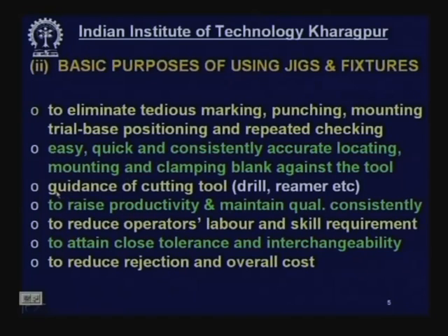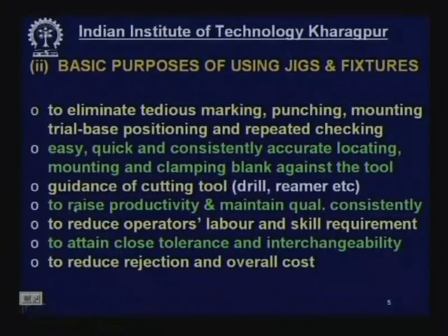In addition to that, guidance of the cutting tool like drill, reamer, some say boring tool also, special type, or say countersinking tool, which are slender in nature because of the cantilever action, then they have to be guided by bush to raise productivity, because the work will be much faster, and maintain quality consistently. So, the quality will be repeatedly maintained, there will be no variation piece to piece.